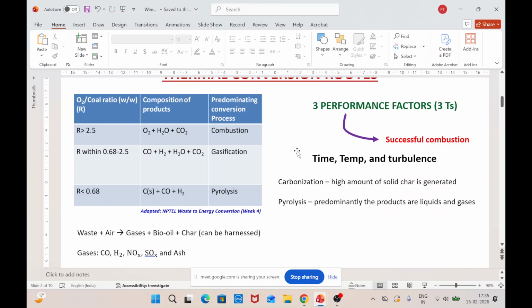So this is something we discussed prior also, right? High oxygen content means the HHV value, that is the high heating value, or you can also say the amount of energy that the bio oil will carry, will be very less. So in order to produce a particular amount of energy, more quantity of bio oil is required. Economically speaking, it is not a very viable option. So these are the disadvantages of the bio oil.